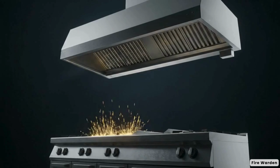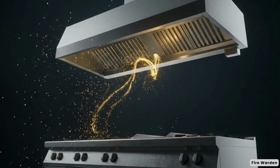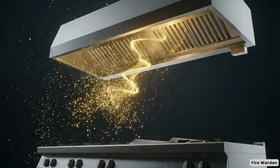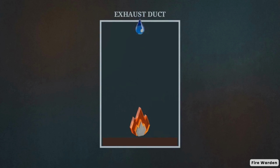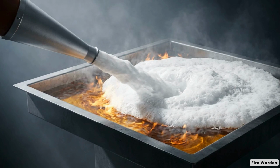In commercial kitchens, the hazard is airborne. This slow-motion visualization tracks microscopic grease particles aerosolizing above a stove and traveling into the extraction hood. Without strict, regular maintenance, those grease particles accumulate inside the ductwork, creating a flammable tunnel running through the building. Should that grease catch fire, standard water extinguishers will spread it. It requires a Class K extinguishing agent to smother the liquid fat through a chemical reaction called saponification.